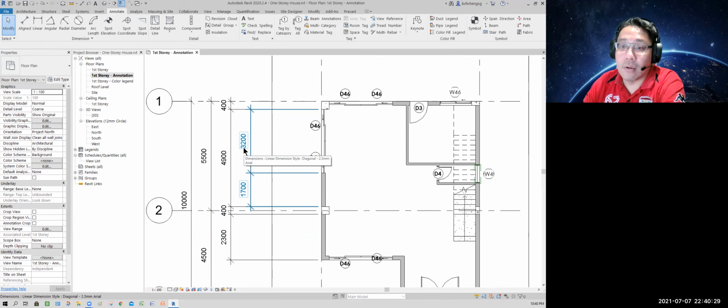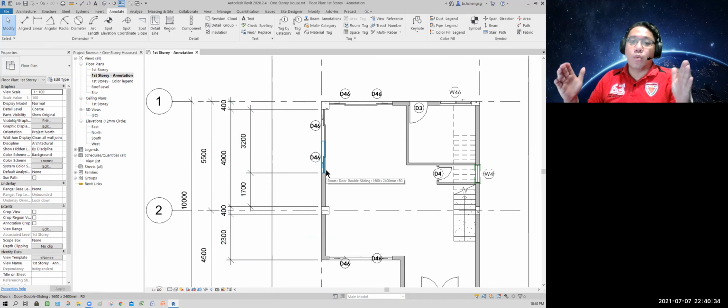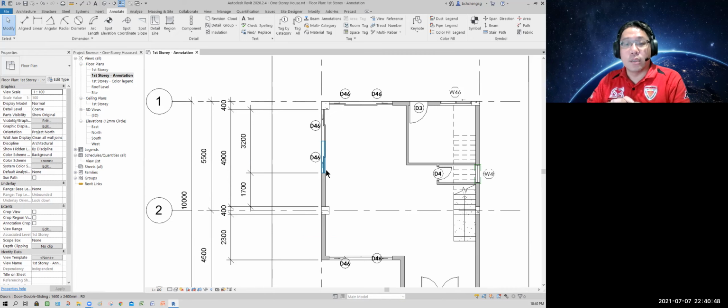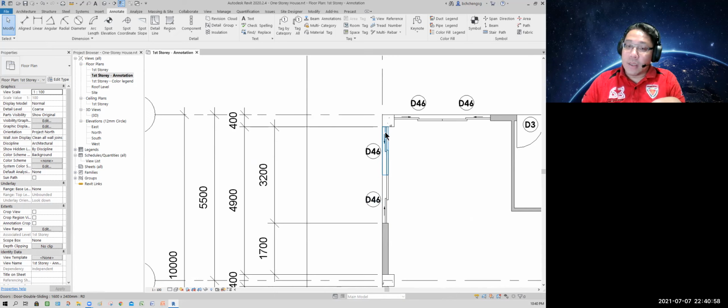3002 structure opening, correct or not? Yeah, but again, our door and window normally we have a clear opening, we have a structure opening. But of course, to the window contractor, you have to provide them the structural opening, not clear. Clear is architect specified, then they know what to adjust. Then, when you build the library family, all these frame size, jam size, whatever must be accurately modeled.